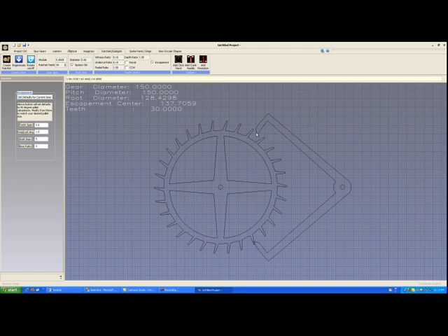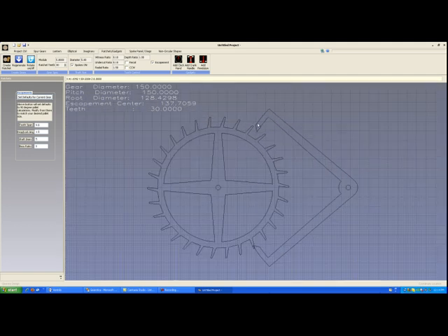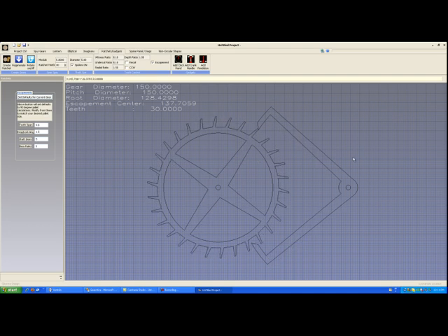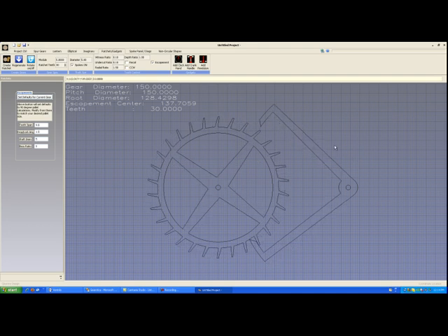Changing this angle unnecessarily one way or the other will reduce power quite quickly to what gets transferred to the pendulum. This is because you're trying to rotate a force which is going in a tangential direction to the deadbeat to a force which is tangential to the pawl. And this rotation of energy loses quite a bit in the translation, so you're 50% efficient. Again, if we hit rotate, you can see that everything works as before, but we have a longer center distance.